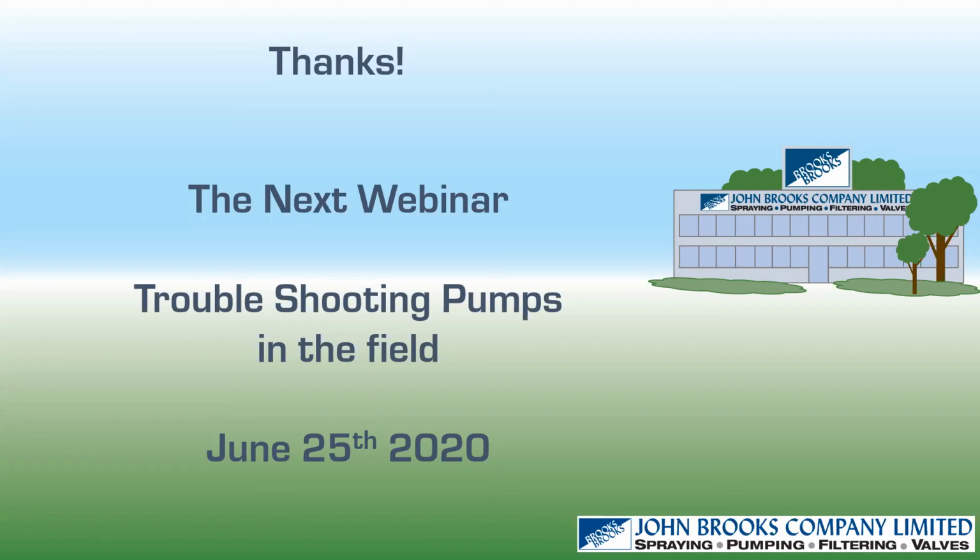Now, just one little point there. Up to this point, we've been just talking about 3-phase induction motors, and that's what we deal with pretty well every day. Could there not be some other types of motors out there where these relationships are slightly different, Adrian? Well, we're never going to violate that horsepower equals torque times RPM relationship. That has nothing to do with motor design or anything electrical. It's a mechanical relationship. We might get better efficiencies out of other types of motors, but I think about 95% of the world's motors are induction motors just because they're so cost effective and they run very well.